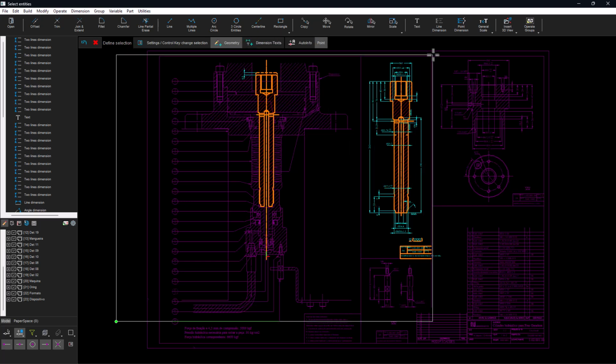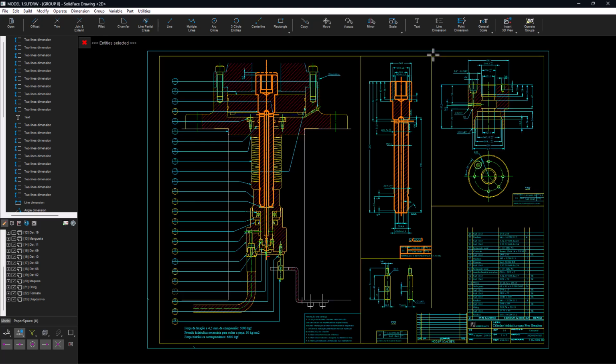When creating an entity in an active group, you can use geometric information, midpoint, extreme, etc. from any passive groups. However, when referencing geometric information from passive groups, this information is not auto-associative. In other words, when modifying an entity in the active group, this modification will not be automatically associative with the geometry that referenced it in a passive group. Auto-association will always be possible in entities created in the same active group.